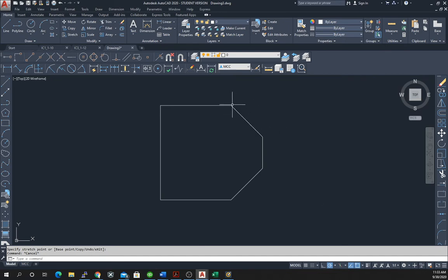Now when you drew these lines in, you could also draw these lines in using the polar reference. And let me go and real quickly show you how to do that. So I'm going to delete this line. And if I want to draw this line in using a polar reference, I click here to start the line. And then remember, I don't know how long the line is, but I know it's less than 2 inches.